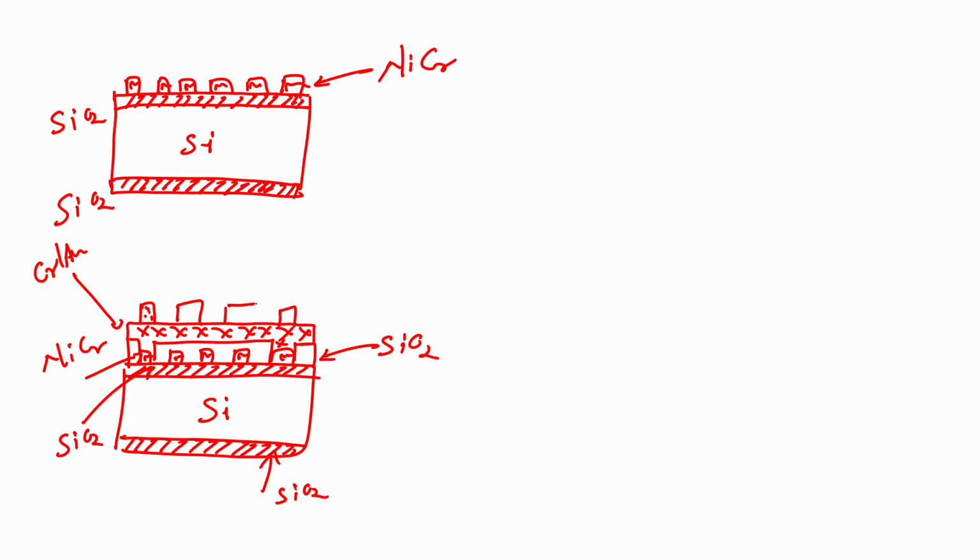and then, right. After this, I etch this wafer, etch chrome and gold by dipping the wafer in etchant. First is gold etchant followed by chrome etchant, because chrome is at the bottom. So, first I will dip this wafer in gold etchant followed by chrome etchant.